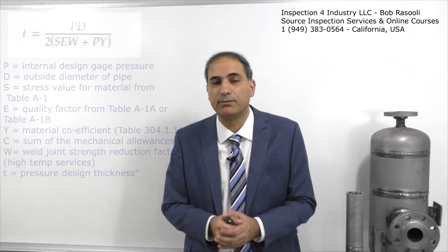They have different code committees, and they sit together to see how they can get the higher thickness for safety factors. The safety factors for a pressure vessel might be different from process piping, but the way they add these safety factors causes the design formula from one code to be different from the other.